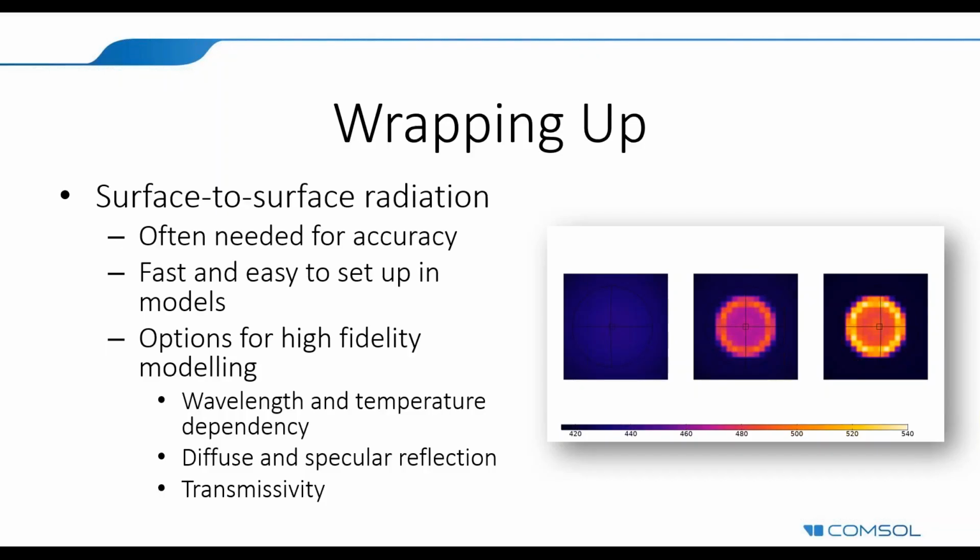And there are a number of options that we have introduced for high fidelity modeling for surface-to-surface radiation. So the wavelength and temperature dependency, the different kinds of reflection, diffuse and specular, and the transmissivity. So I hope that will be helpful.